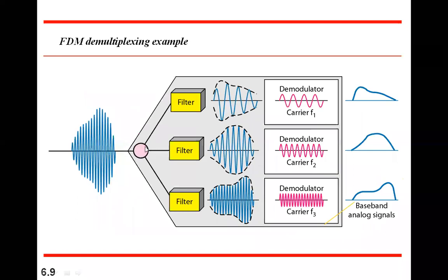Here actually come the intermodulation products, because so many signals are mixed here. That's why we have to take care of intermodulation carriers also. They should not go beyond a certain level, otherwise they will cause more interference with the system.